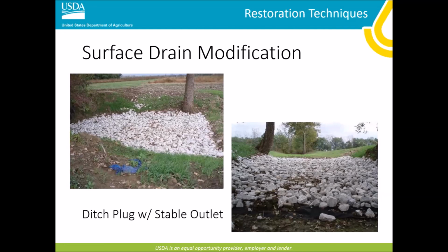In a floodplain situation, flood water might back up across the opposite direction the ditch is normally flowing and cause scour on the other end. So it's very important to look at that. To design this, you'll really need to look at our grade stabilization conservation practice standard to look at how we adequately design this structure on the outlet and the inlet of these ditch plugs.